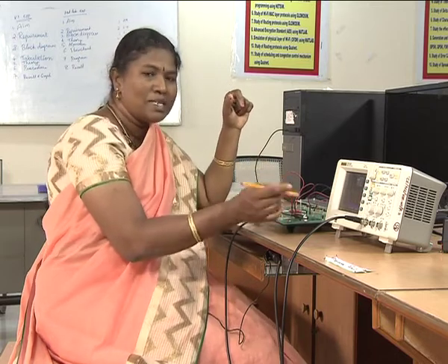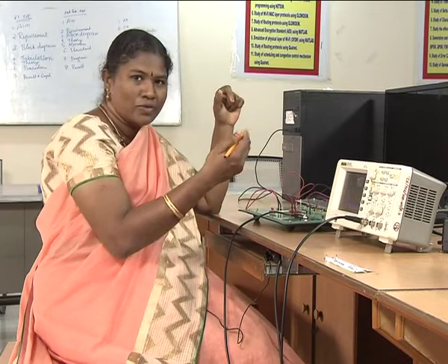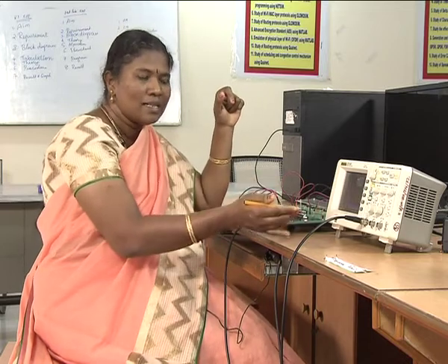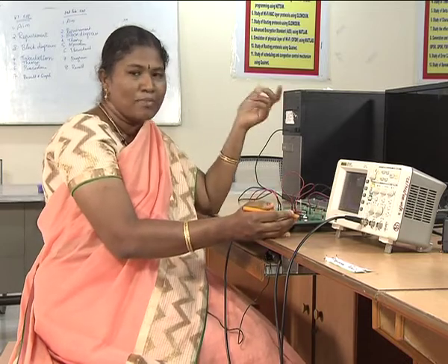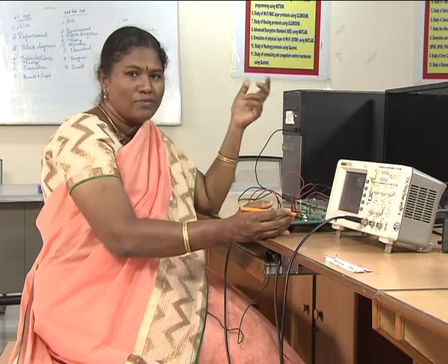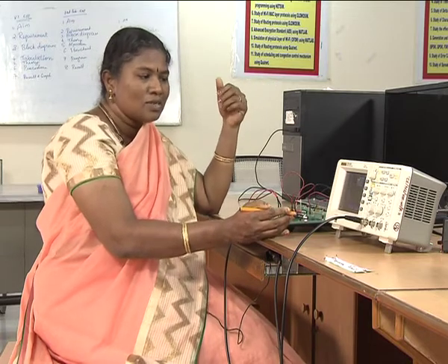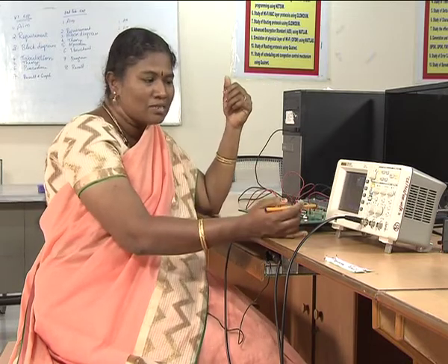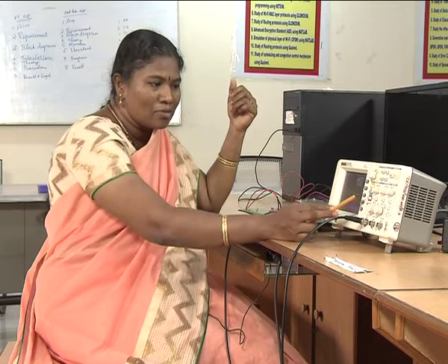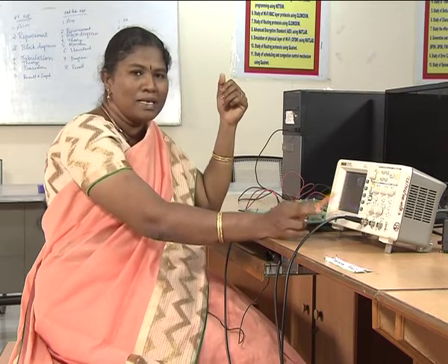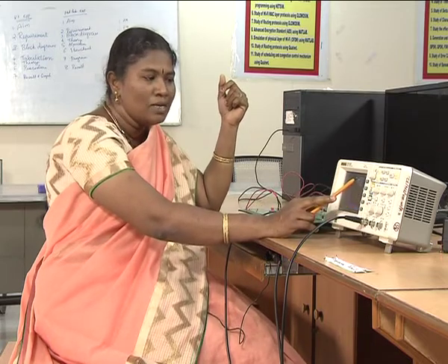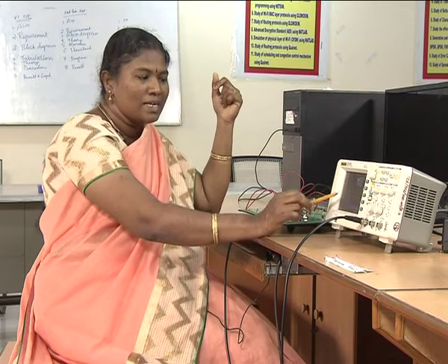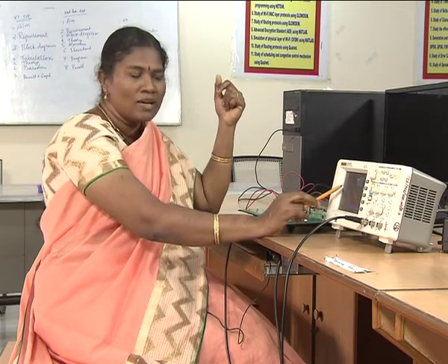Once you have noted down the time domain waveform, you should go to the frequency domain of the signal, so you can find out the bandwidth required for transmission of this FM modulation. To get the bandwidth required for transmission, you have to use the math operation. In the math operation, you will have the FFT mode. Once you select the FFT mode, we get the frequency spectra of the FM modulated signal.